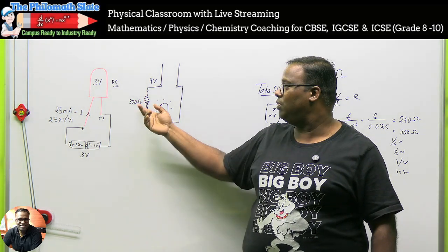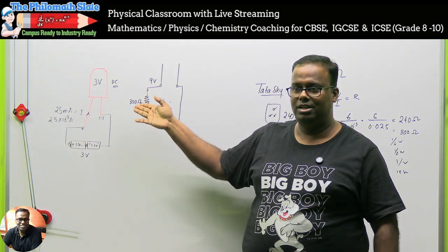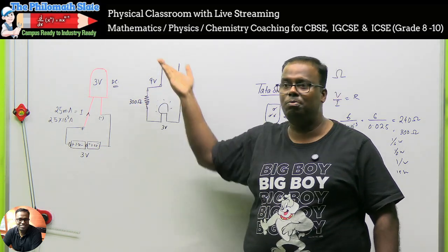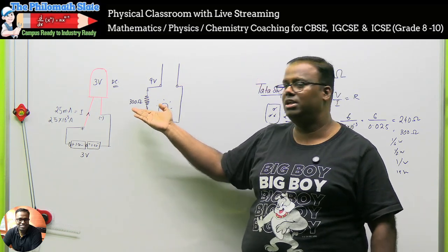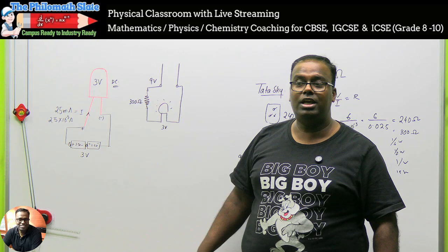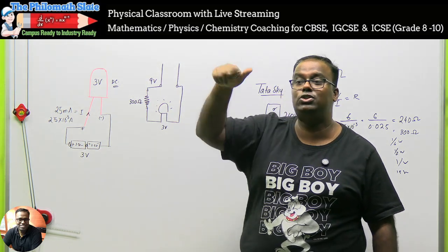We have to first calculate how much power is dissipated here, as heat. And what is power? Energy upon time. That's your next section of study. Once you calculate that the power here is, say, P watts, then again be the mother. Don't buy a P watts resistor. Buy something like 2P.